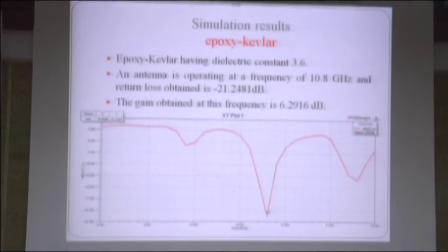If I am using epoxy Kevlar, then the resonant frequency or the operating frequency is 10.8 gigahertz, the return loss is minus 21.2481 dB, and the gain obtained is 6.2916. So we can see that the dielectric constant is reduced but the gain is increasing here.